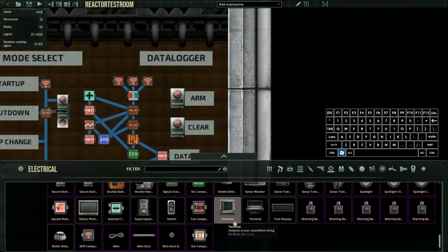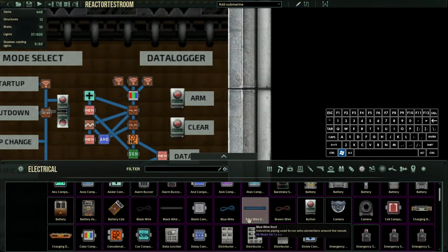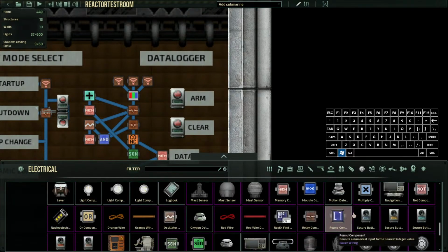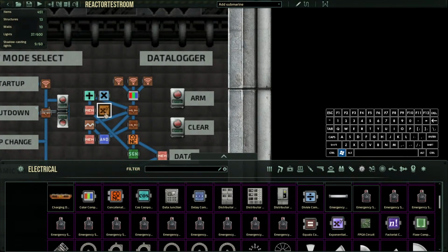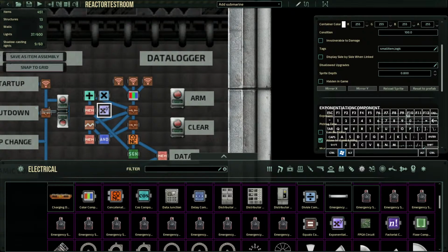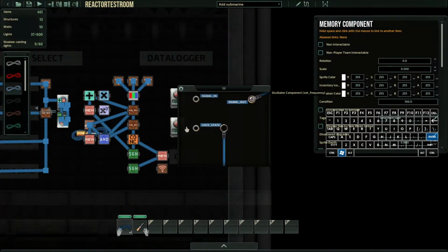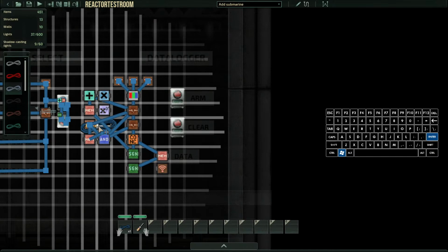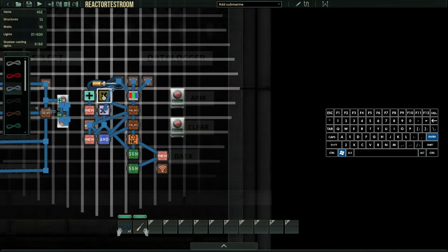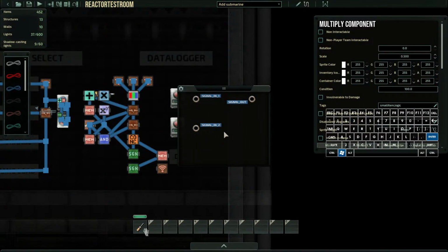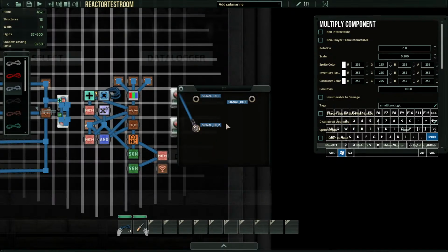And then we can put 2 more math components here. We need a multiplies. And we need exponential, and call this -1. So what this is going to do, so if our frequency is 20 hertz or 20 times per second, -1 means it's a reciprocal or an inverted fraction. We put that 20 hertz into here. That turns that into 1/20th. And we plug that into here, which multiplies the value of the memory block, which is the number of ticks.